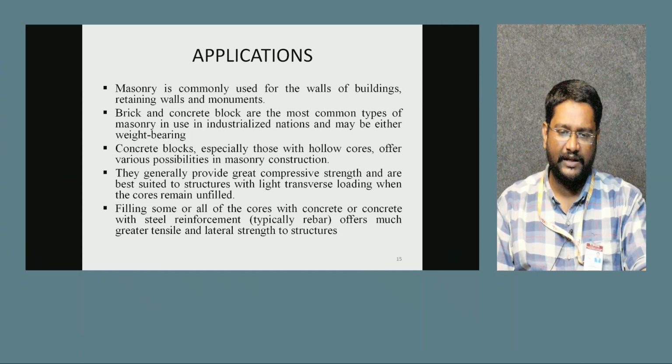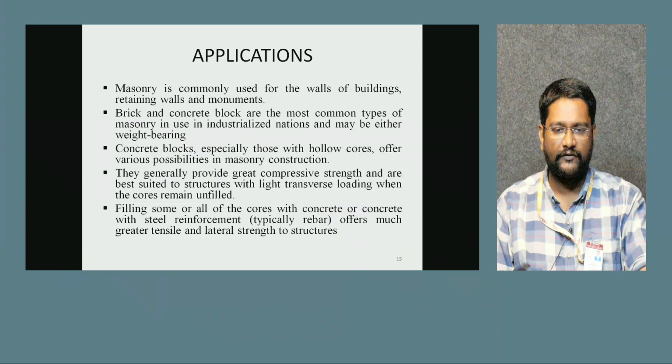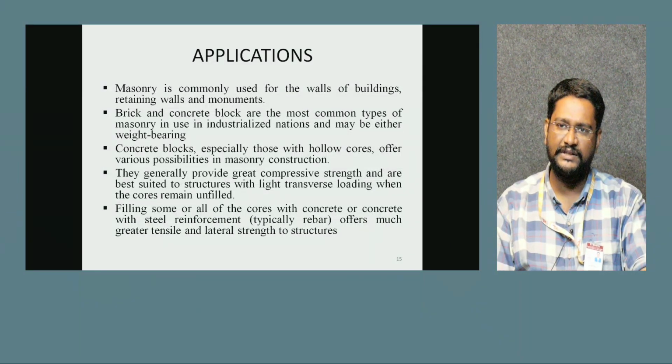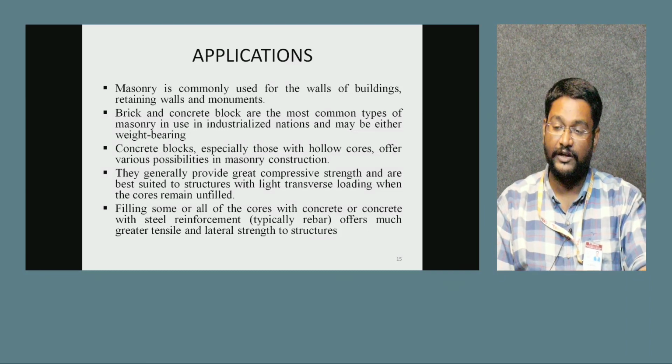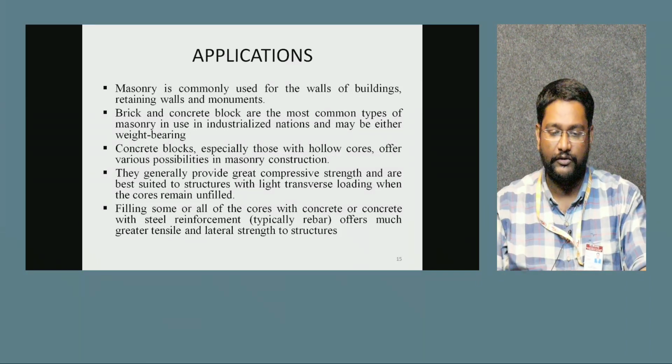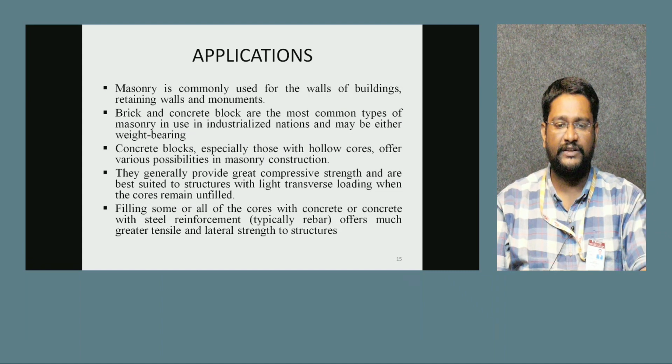Because of that vacancy we reduce the weight of the structure. Filling some or all of the cores with concrete or concrete with reinforcement, typically rebars, offers much greater tensile and lateral strength to the structure. For example, if we are using blocks only for partition walls, there is no need to fill the cores. If you are going with load bearing walls, we have to fill the cores with different materials, maybe reinforcement, maybe concrete.